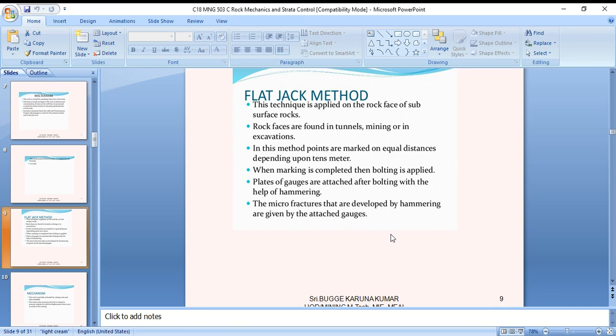The most probable value of an experimentally determined quantity is the arithmetic mean, which is the sum of the individual readings divided by the number of readings. If the number of readings is large, the average approaches the true value of the measurement. However, neither the sensitivity nor the reproducibility is an indication of the accuracy of the instrument. The accuracy of an instrument can be determined by measuring or comparing against known standards.